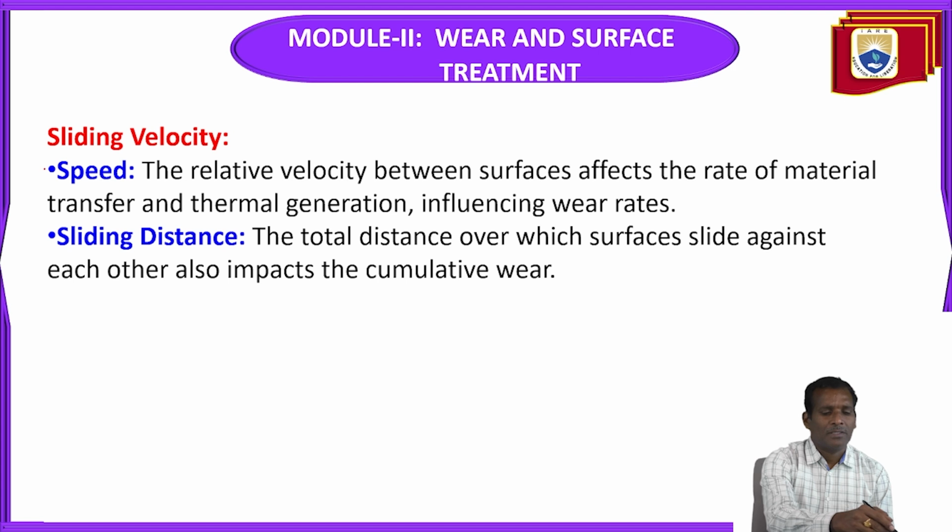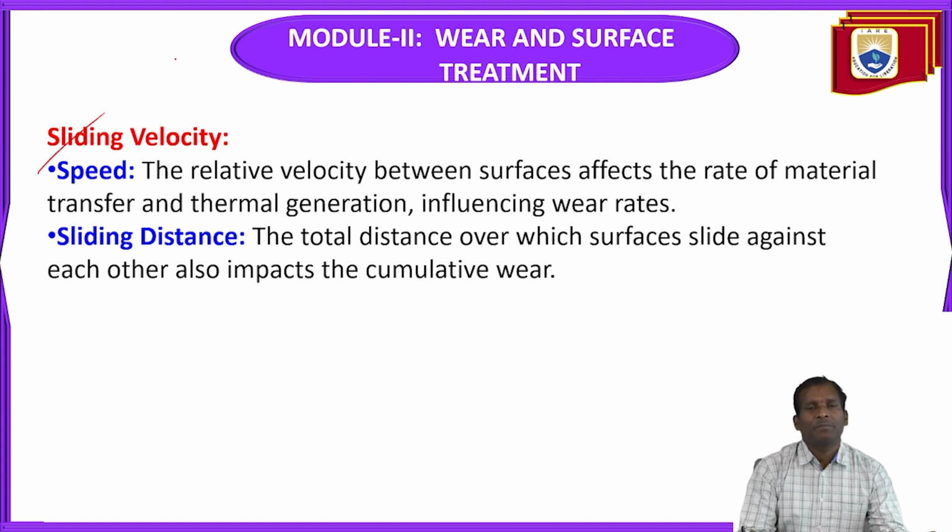Next, sliding velocity or speed. The relative velocity between surfaces affects the rate of material transfer and thermal generation, influencing wear rates. The sliding distance, the total distance over which surfaces slide against each other, also impacts the cumulative wear.